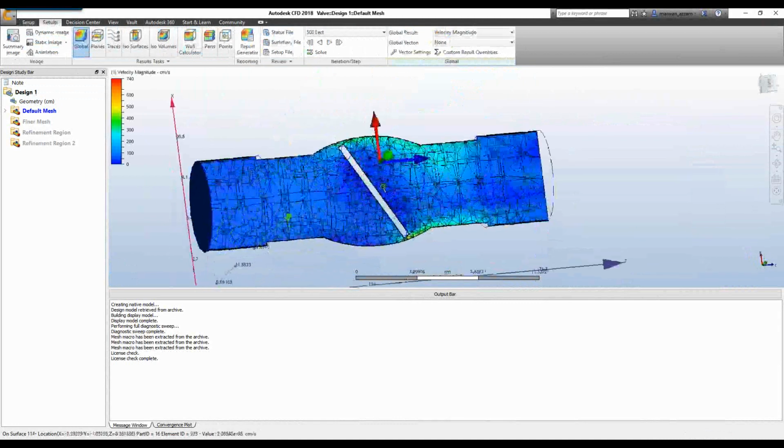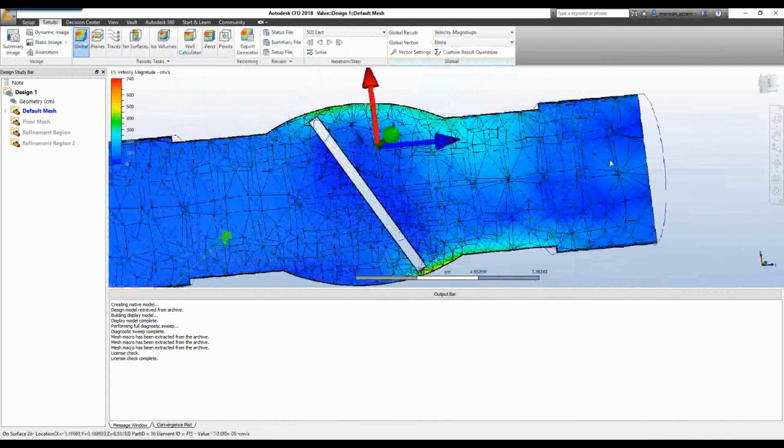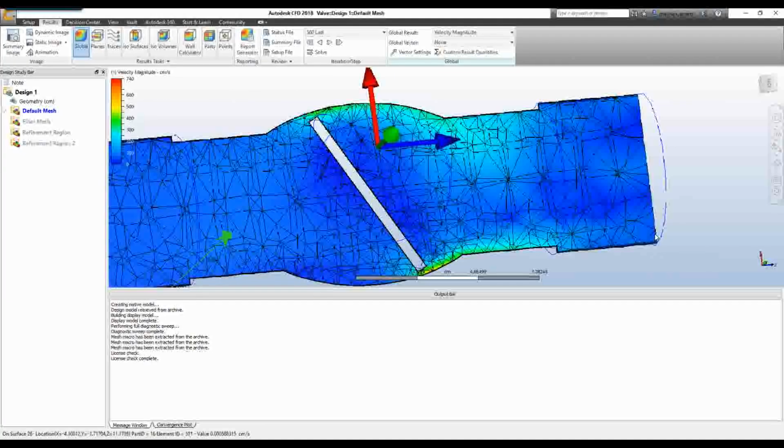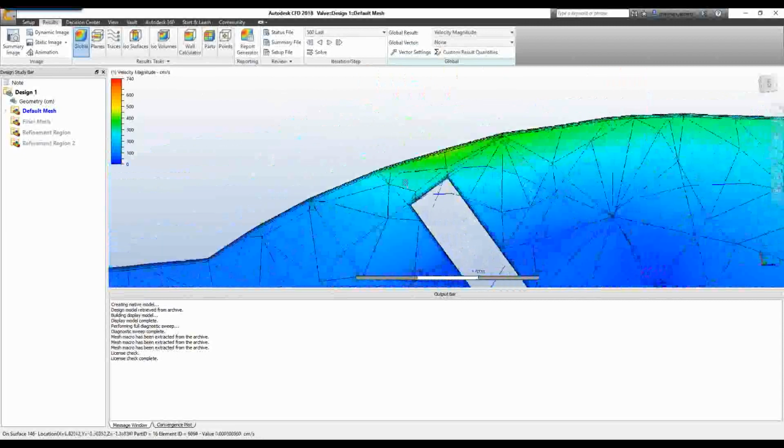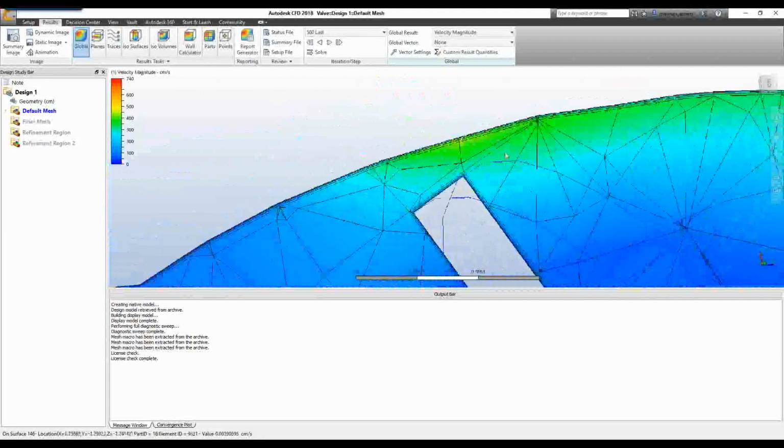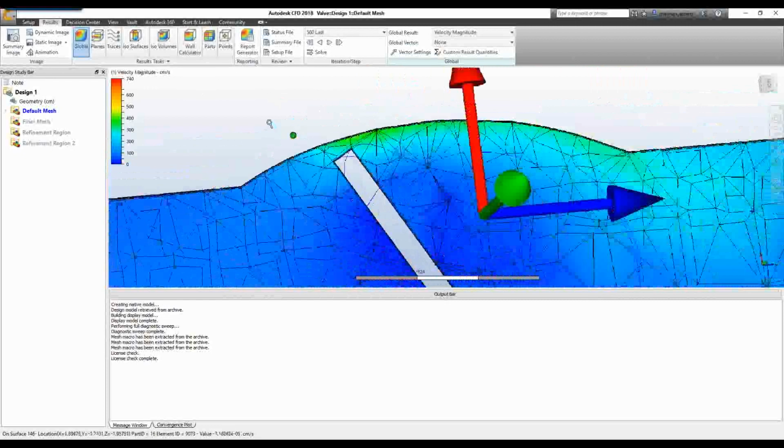at the geometry, it's represented pretty well. There's no fine detail in the geometry that I'm not going to be able to capture unless I have a fine mesh. However, if we look inside here, you can tell right away that it's really not so good to represent the flow in this smaller gap. So right from the start, you might want to refine it.